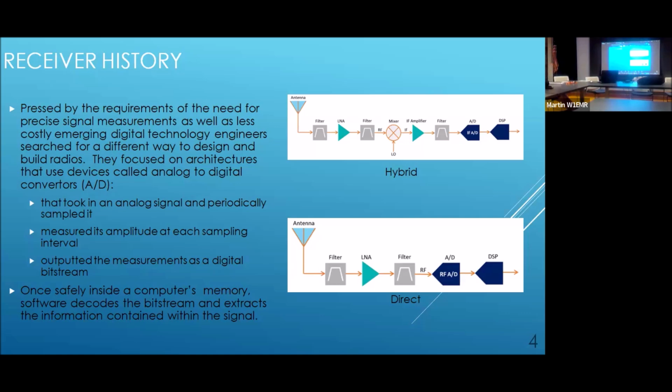Why do we do this? That looks pretty complex, and it is. But we do that because analog to digital converters at the time were ridiculously expensive, and the resolution was pretty poor. So by making the frequency that they'd have to work at a lot lower, we could put in a reasonable cost A to D converter. And a lot of rigs use this technology, the so-called hybrid.